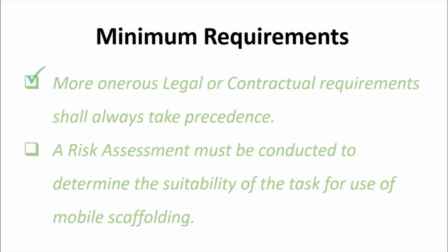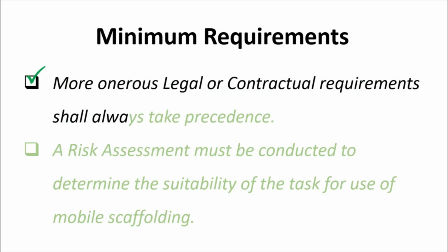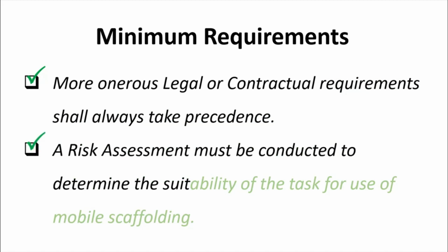Minimum requirements. More stringent rules, legal or contractual requirements shall always take precedence. A risk assessment must be conducted to determine the suitability of the task for the use of mobile scaffold. So we need to make sure that we are complying with the legal and contractual requirements for the erection, alteration, and dismantling of the mobile scaffold.